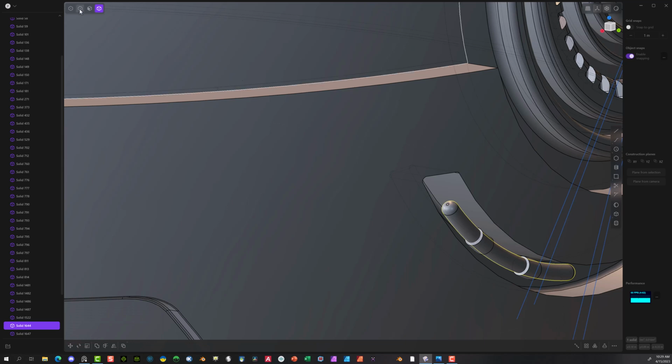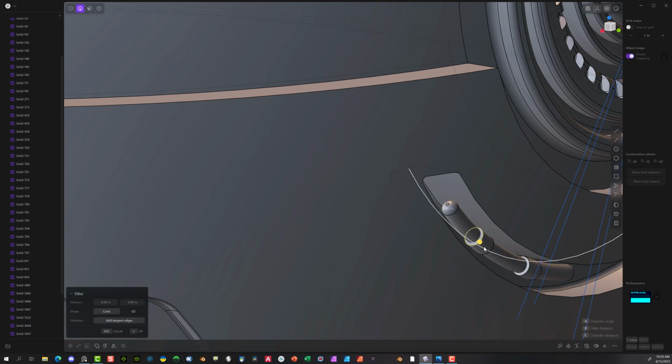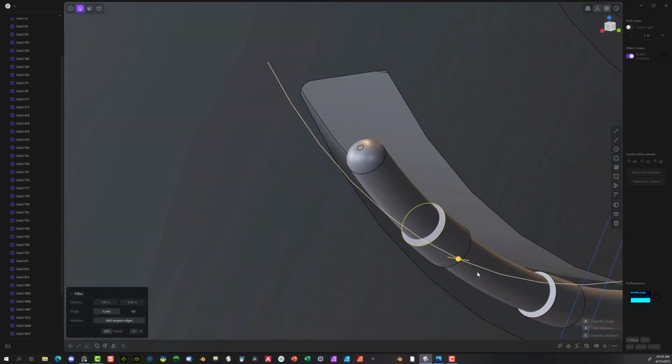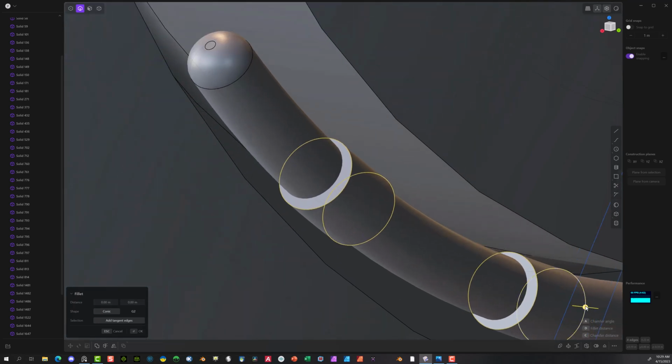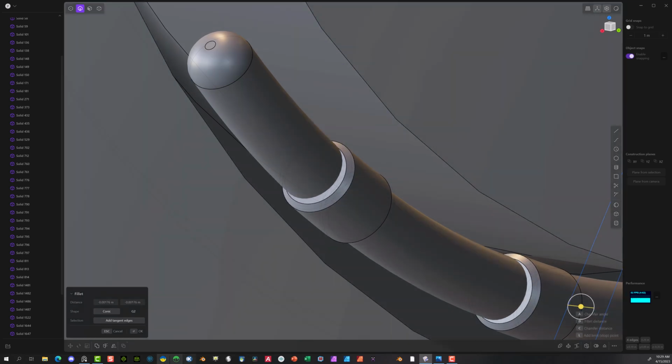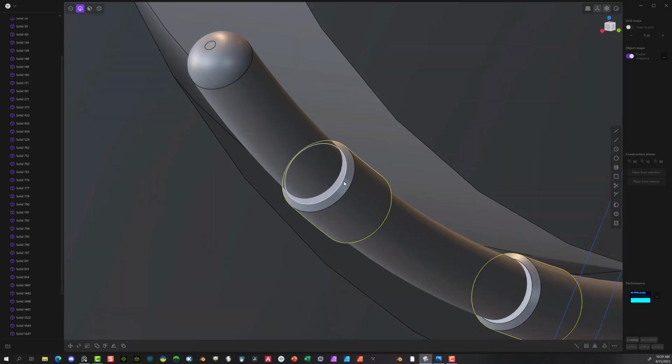Now I'm going to actually use the edge tool. Give this some variation. Hit the control key. Okay, let's do this again. Hit the shift key on these 4. Let's go ahead and give it a chamfer. Something like that. Now hit all 8 of these.